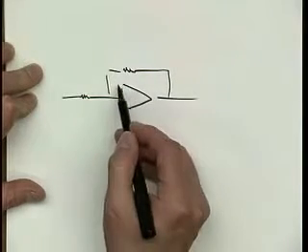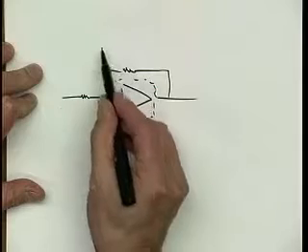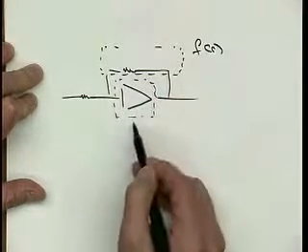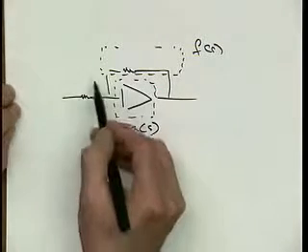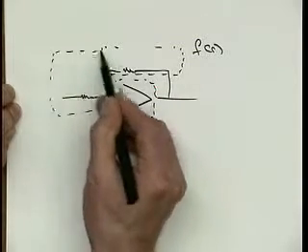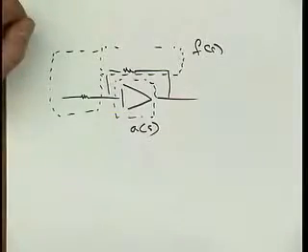And you break it up into this port and this port, and you call this F of S and this A of S, right? And this one you somehow also need to include into the feedback circuit. Okay, and that would be shunt-shunt feedback.